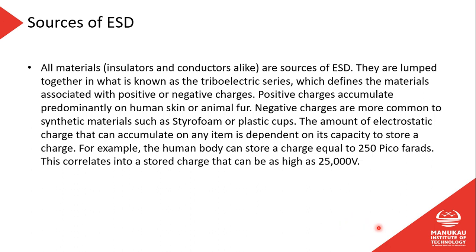All materials are sources of electrostatic discharge. They are lumped together in what is known as the triboelectric series, which defines the materials associated with positive or negative charges. Positive charges accumulate predominantly on human skin or animal fur. Negative charges are more common on synthetic materials such as styrofoam and plastic cups.